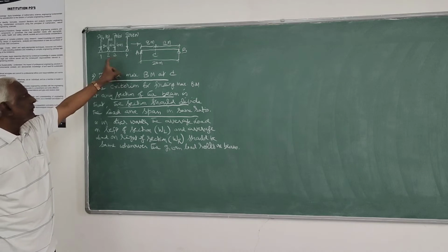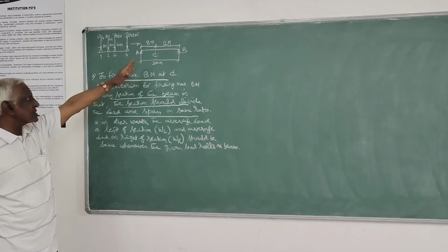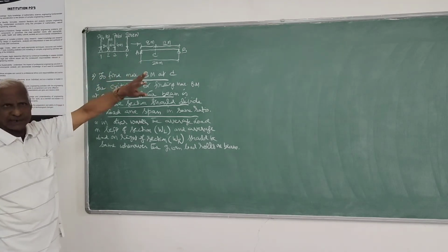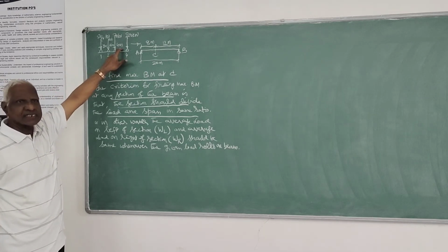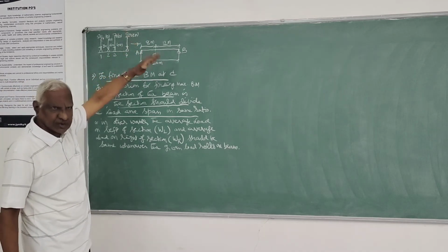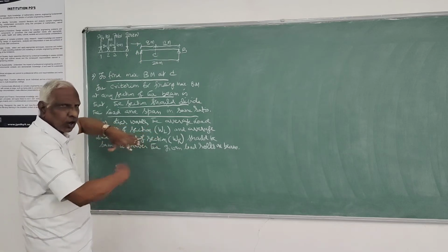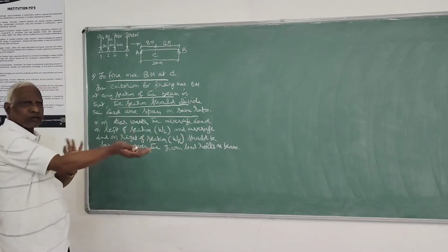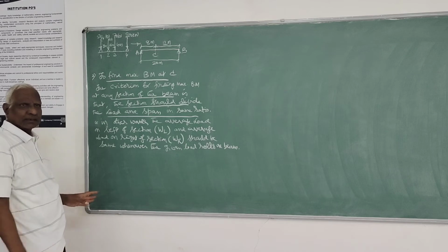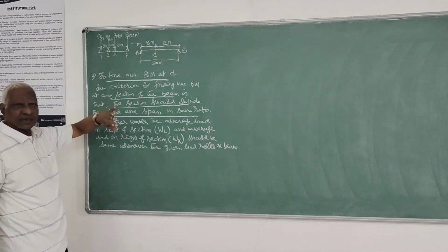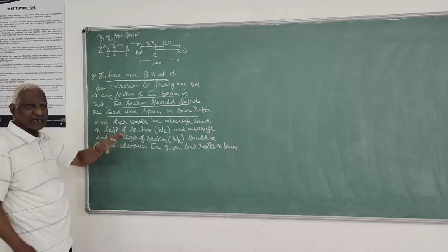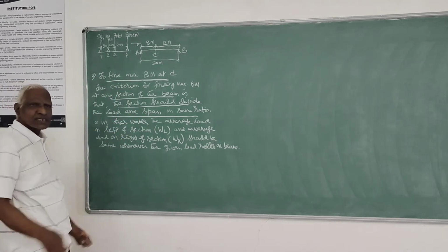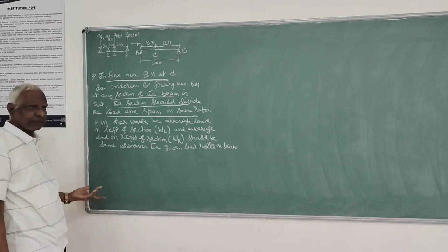If you take the load to cross the section from left to right, then you have to place first the right extreme load at C, first trial. Then you go on allowing one by one, finding average loads on either side of the section, dividing the total load on the left and right side by the respective spans.